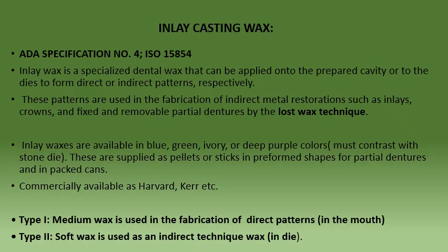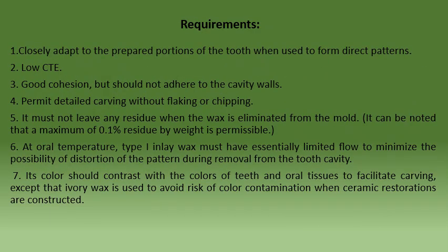So for that, you need to have an adequate flow. So for that, you can use a soft wax. So basically, this is very important: medium wax, soft wax. Medium wax for direct pattern, soft wax for your indirect pattern. Again, the requirements are same.